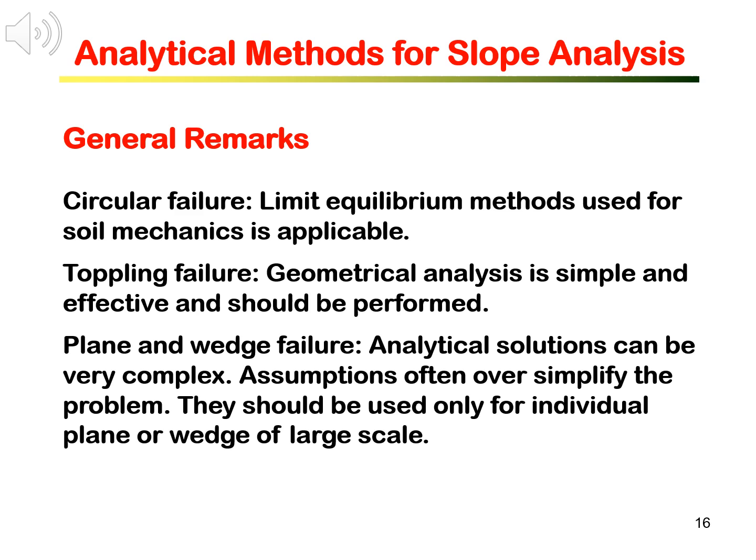Analytic methods can be used for plane and wedge failure. However, the solutions can be rather complex. Assumptions often oversimplify the problem, and the important factors cannot be analyzed. Analytical methods should be used only for single individual plane or wedge of large scale.